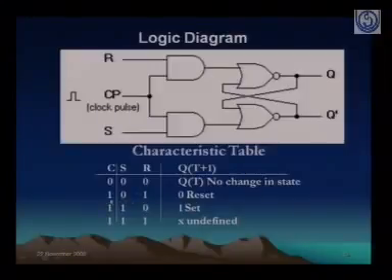However, the next two rows represent the reset state first. A clock pulse occurs, the S value is 0 and the R value is 1. So on the occurrence of the clock pulse, the flip-flop goes to the reset state. That's what we saw in the latch, right? That means the value of Q becomes 0, and the value of Q dash becomes 1.